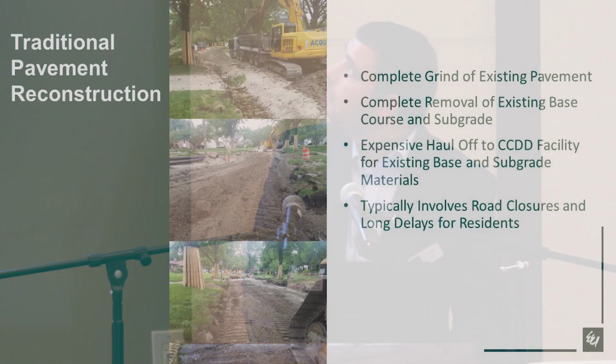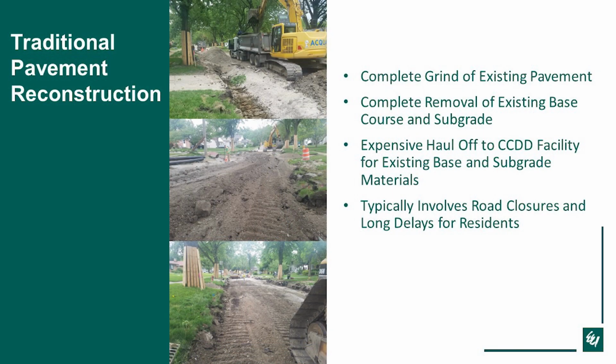So based on the information that was discussed earlier, if we determine that the pavement reconstruction is the correct route to go down, then you'll have to completely grind off the existing pavement, and then you'll typically have to remove and replace the existing base course, proof roll the subgrade, and maybe make repairs to the subgrade. Obviously, this is typically a very lengthy project. It takes a long time for the contractor to remove all the material, get it all graded out, and has a great impact and effect on the residents.